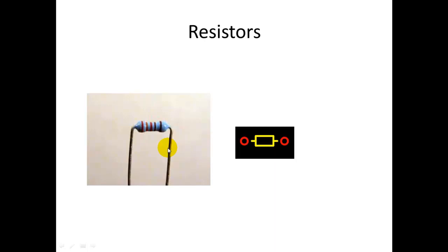On the bottom of the circuit board we need to have annular rings made out of copper on which the components will be soldered. Over here on the right you see these two annular rings. The rings in red represent copper on the bottom side of the board, so we have one annular ring here on the left for the left lead, and another annular ring on the right for the right lead of the resistor.